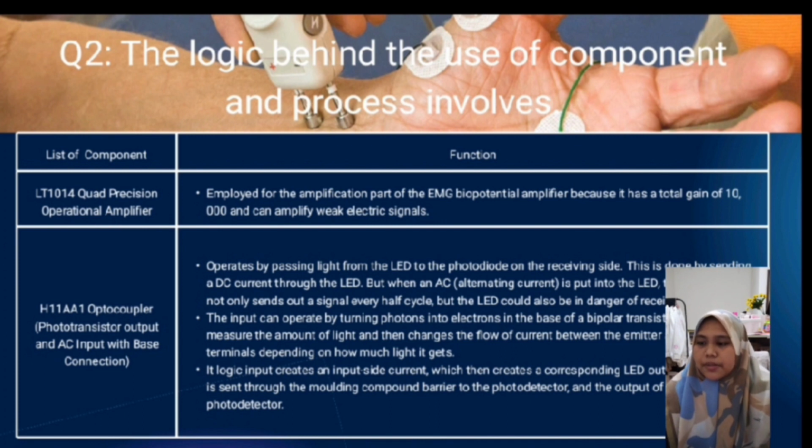The differential amplifier boosts the voltage difference between the 2 sources of the EMG signal picked up by the bipolar non-invasive skin electrode. The input buffer is used to transfer a voltage from a first circuit having a high output impedance level to a second circuit with a low input impedance level. The interposed buffer amplifier prevents the second circuit from loading the first circuit unacceptably and interfering with its desired operation. While the other one left is used for voltage follower, which has a gain of 1. This provides very high input impedance and isolates output from the signal source, hence avoiding the loading effects.